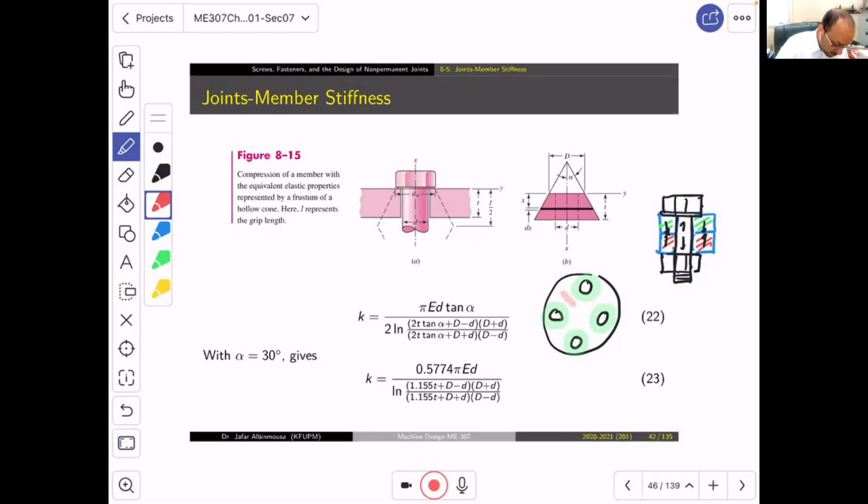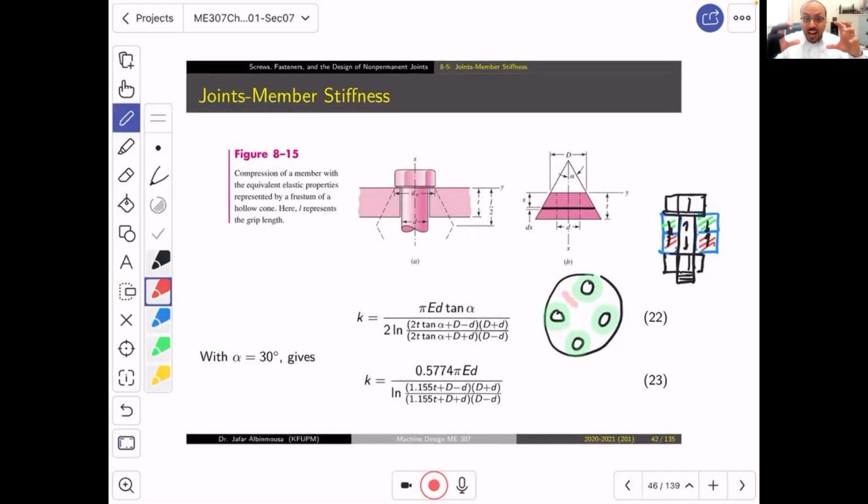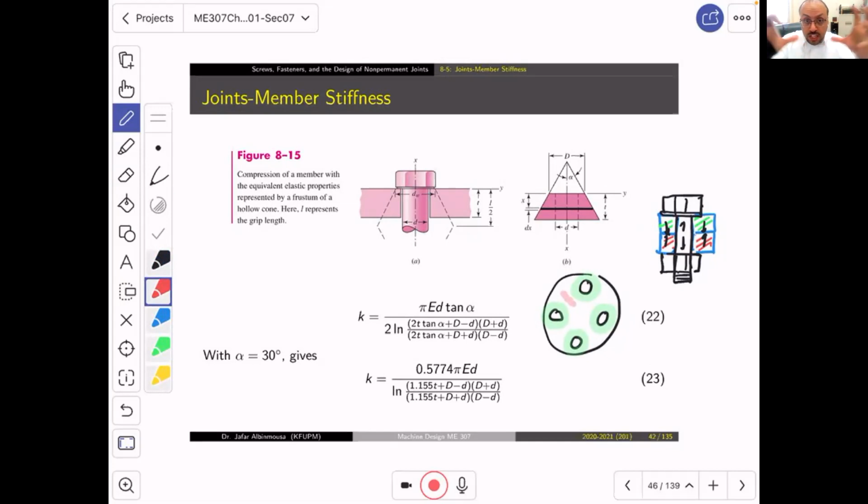Well, sadly enough, this part doesn't have the propagation of the clamping force around the bolt. It will not permeate, guys, it will not spread all over the earth. It will have a physical, small, confined space. And for that reason, what will happen? If you have a fluid, gas, whatever, it will leak from here. So what should we do? You clamp more. If you clamp more, maybe this green region will expand, but it will not be enough.